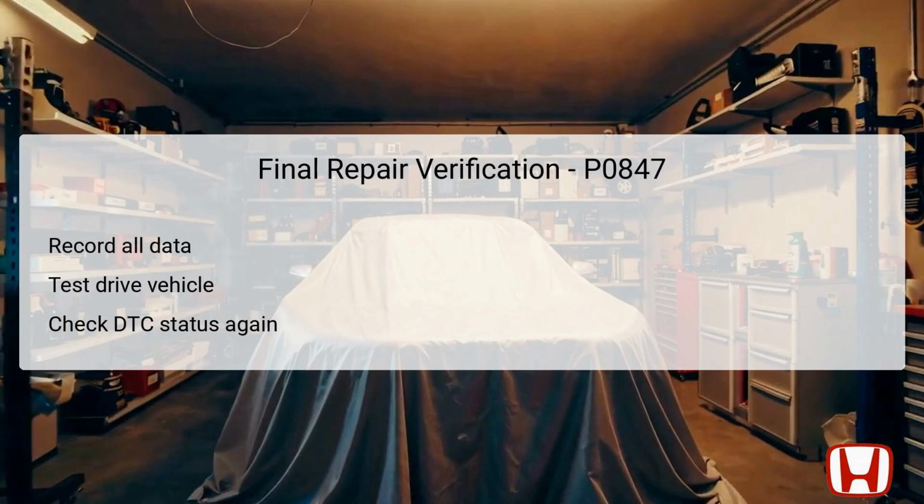After any repairs have been implemented, it is vital to conduct a comprehensive verification process to ensure the DTC P0847 is fully resolved. Start by recording all diagnostic data and any pertinent notes from previous tests to have a clear before and after comparison. Subsequently, test drive the vehicle under various conditions to confirm operational integrity and proper shifting behavior of the transmission. During this test drive, monitor closely for any return of the check engine light or other symptoms indicative of the original issue.